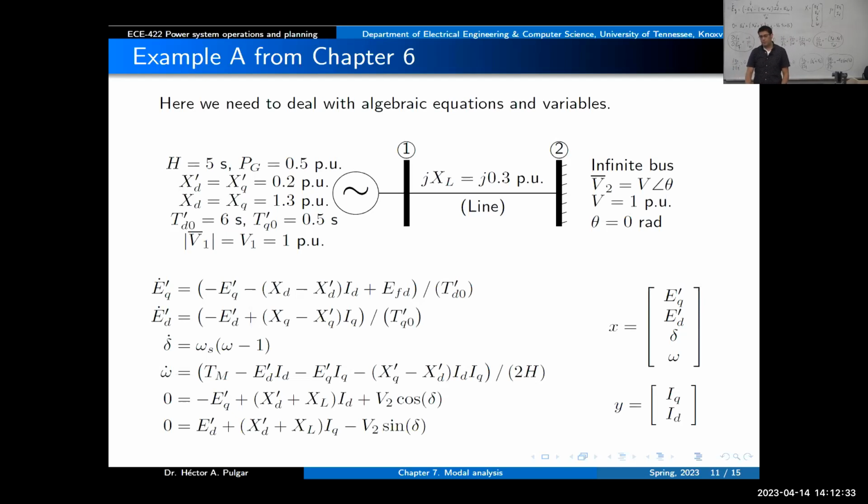Well, if you have less inertia or more power, more mechanical power, there's more energy during the disturbance, so it leads to more acceleration. Same with the lower inertia. So how many equilibrium points does the system have? Very good, David. That's correct. So how many equilibrium points do we have in the system? You're not very sure. Mathematically, it's sines, so a bunch, but yeah, 2. Yes, so infinite, but yeah, perfect. Between 0 and 2 pi for the angle, you have two solutions. What is the solution we pick here?